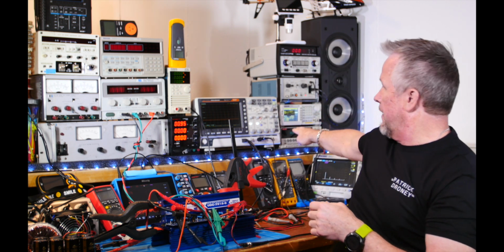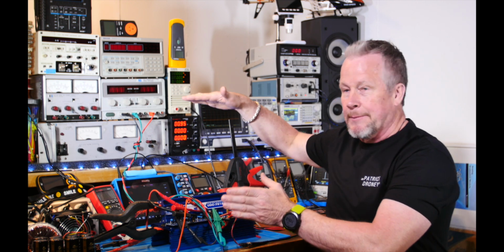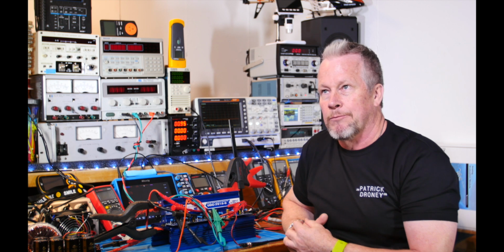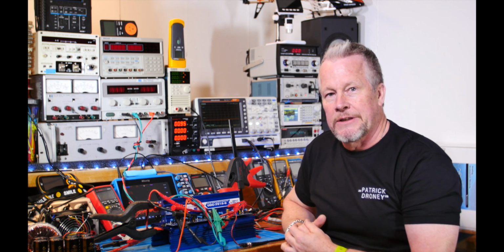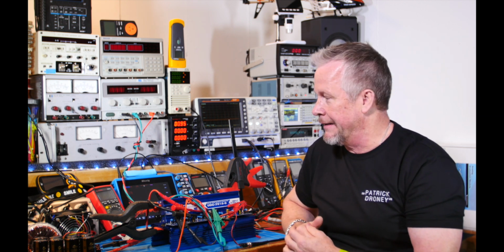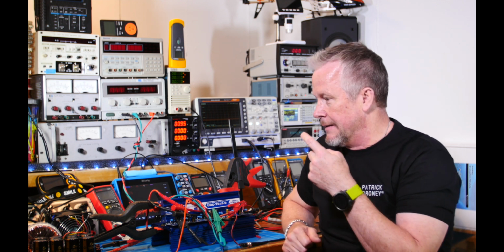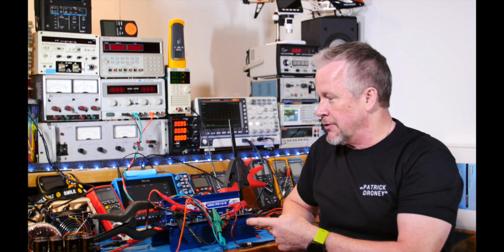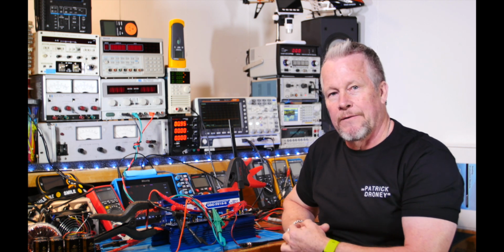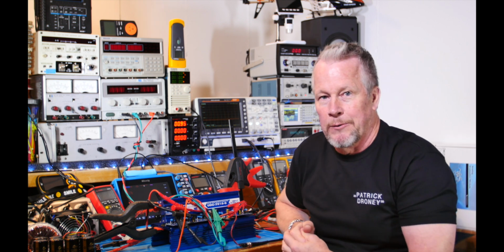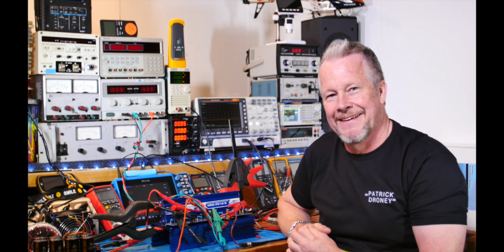Because we did see the Keithley, when we optimized it at whatever levels we were set to, it did put out, what, 0.04% THD. So that's pretty good, I think. What do you guys think for the Class A? I guess we could do some research, see what other people have got in these Aleph 5 Class A's, but I think anything less than 0.1 sounds pretty good.